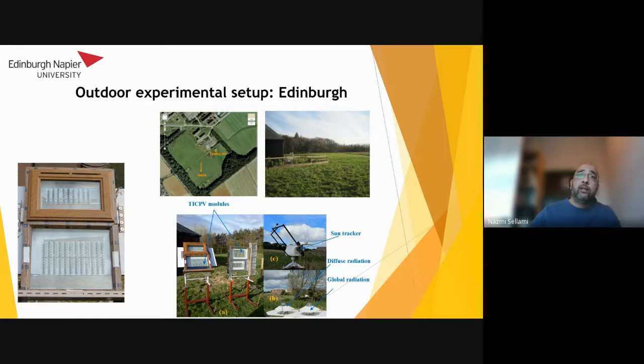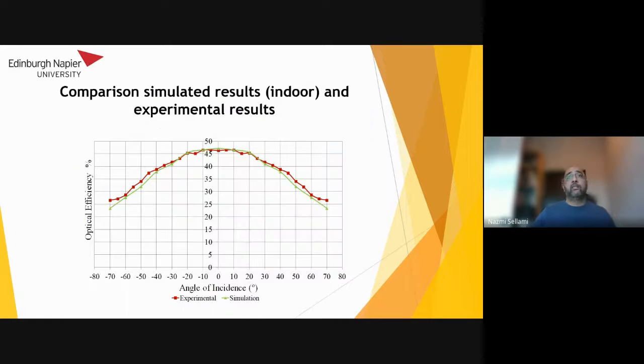design, and the design of the third system, and we came up with these results, where we did some simulation based on the energy generation from PV panels and the optical simulation of our concentrators. As you can see, our optical efficiency can reach 45% when we have an angle of incidence of 0.